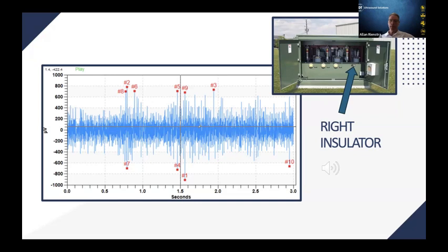because the corona discharge can be created by a breakdown in the dielectric material, or it could be a loose fitting or a loose connection, but it can also be dirt. So if we clean away that dirt with a little dry ice, and we come back and inspect it again, a lot of times that ultrasound signal has now gone quiet. So that's simple maintenance.